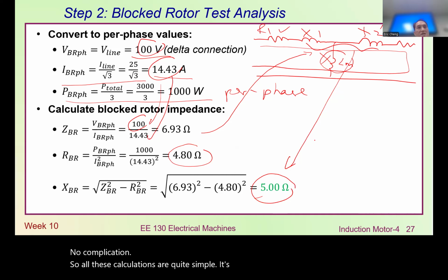So now for the impedance, the voltage divided by the current gives the total impedance for the whole loop here. This whole loop will be 1.979 ohm. After we do that, we also need to calculate the real power, 1.143. These two, using the Pythagorean theorem, give us the x component.